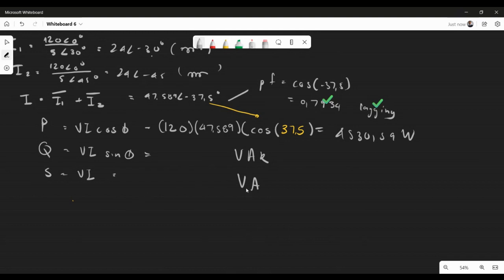So what is my reactive power, Q? Okay, the precise value for us there is negative, and that's very correct. It's very important with the sign there: negative. 3,400 minus 3,476 point something. And obviously this tells you that it's inductive, right?